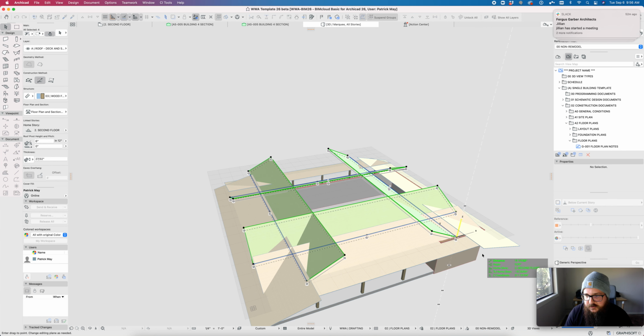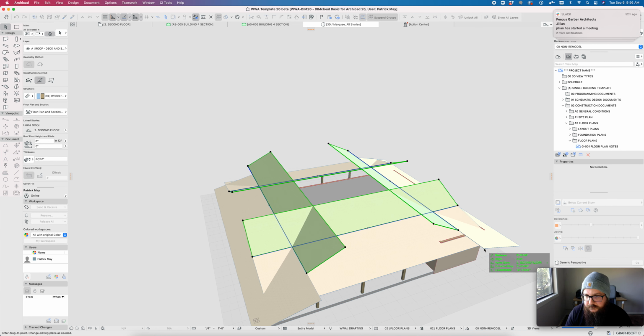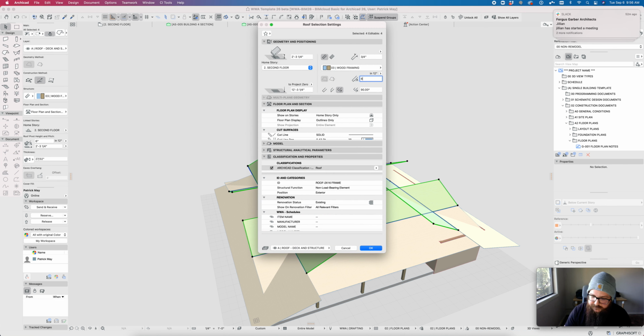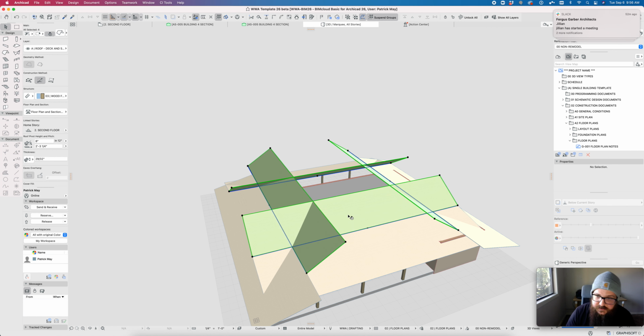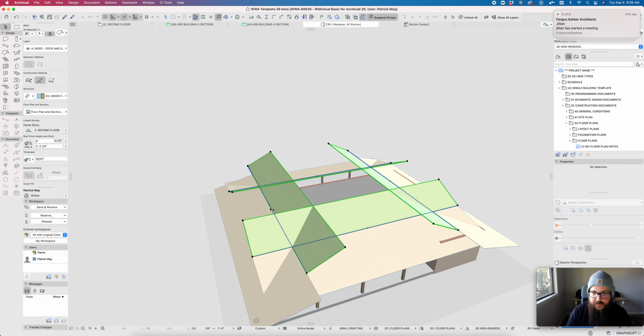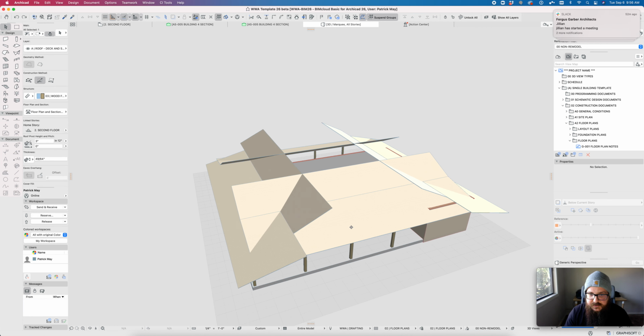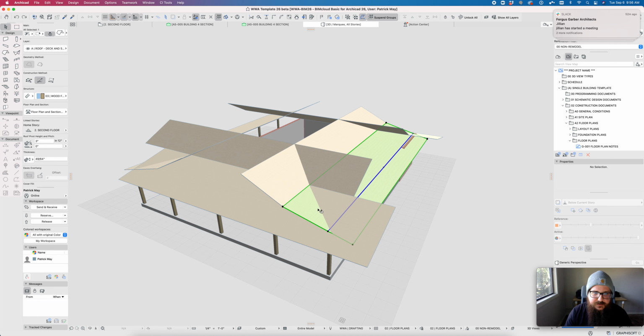So these roofs, dragging vertically, Command D, align at that point. Putting the pivot line right there means that if these roofs ever change slope, if the design process said we're going to look at these as 8 and 12, they're pivoting on that point, so I don't have to raise or lower or elevate them, provided that this lower roof stays where it's at. So we're sort of minimizing, not eliminating, what we're trimming or adjusting.